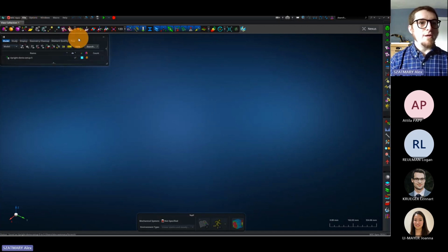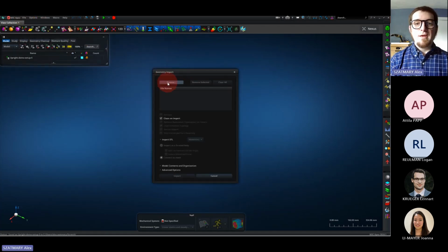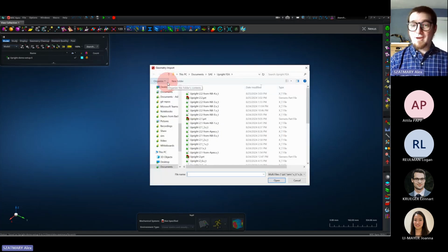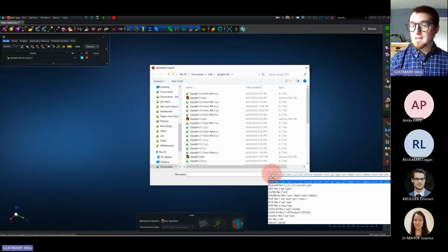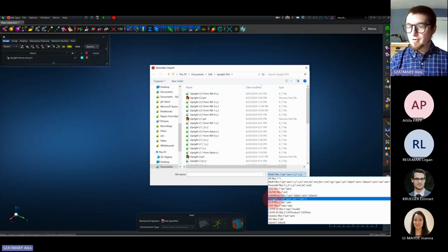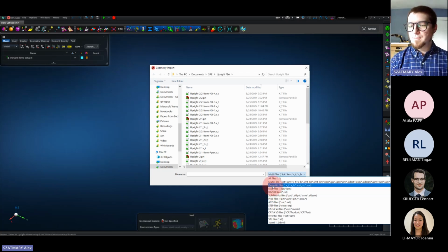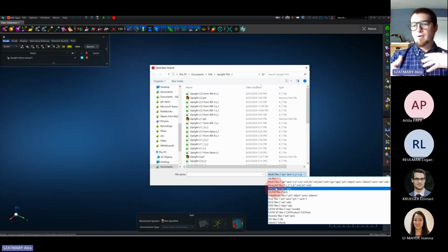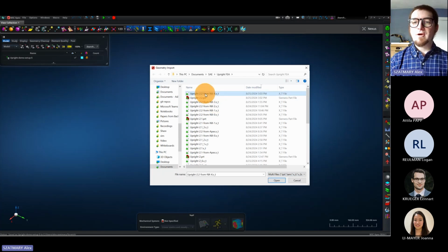One of the most common questions that I get from students is, will I be able to bring my CAD file into Apex? And the answer is almost certainly yes. You see that we support SolidWorks, Inventor, Catia, ProE, NX. We also support formats like Parasolid, Step, IGES, and those are designed to be more vendor neutral and interoperable. In this case, I found that using Parasolid was a great way for me to get my CAD file in.